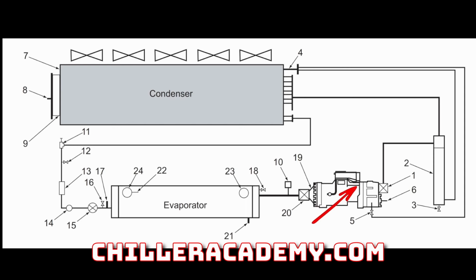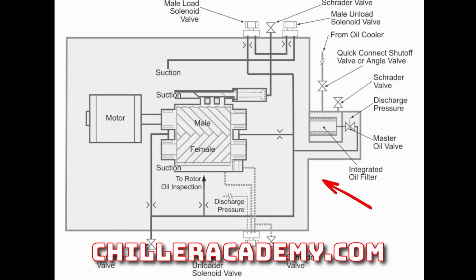So these compressors are going to stage on fully unloaded. Now, something to know about screws is they have a slide valve. We'll go over the specifics and details about screw design, but over here by the motor is your suction side. We're going to pull into the compressor this way and up into the inlet side of our screw rotors. And then that's going to compress through and out into our discharge. And we have this little valve up here. It's called a slide valve.